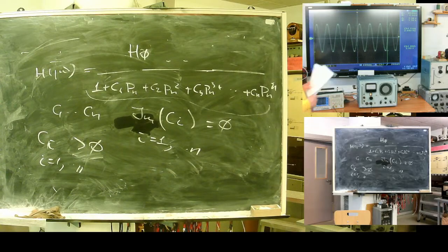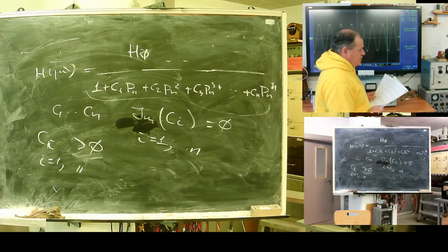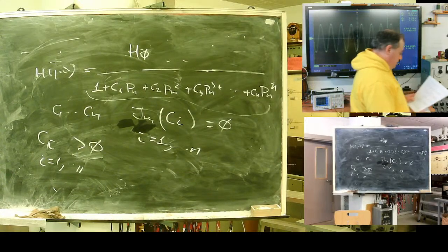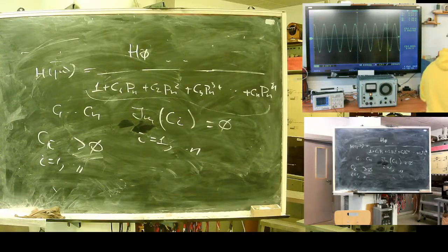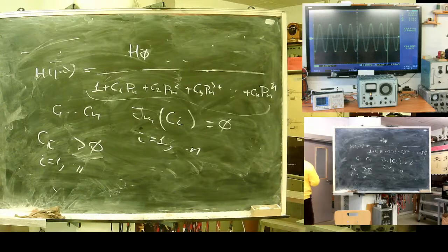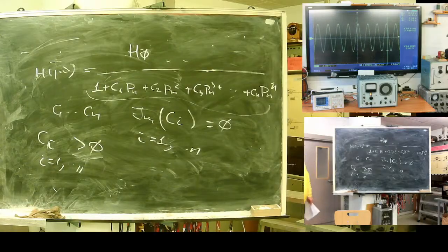So if we can factorize it, this will work. This will correspond to a real existing network, a feasible network that can be created. If you started to create your nice frequency chart and got complex roots, it's a problem. Complex roots means there is no guarantee that you will create this filter.